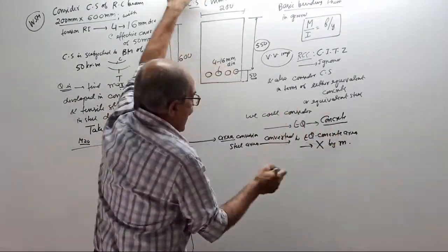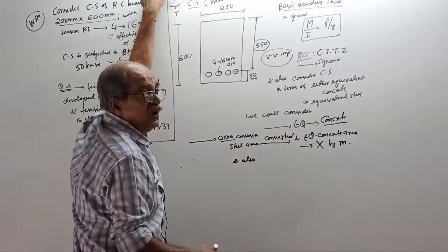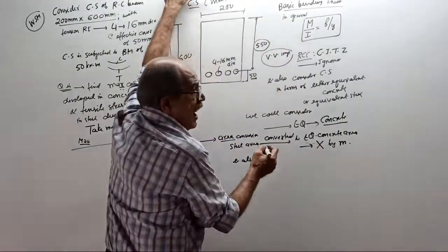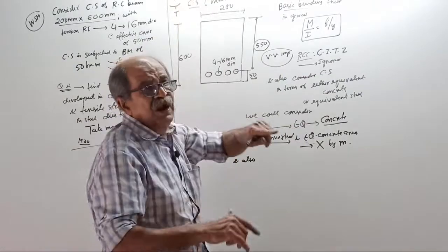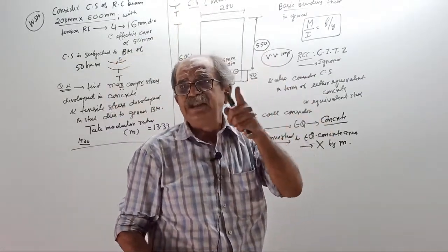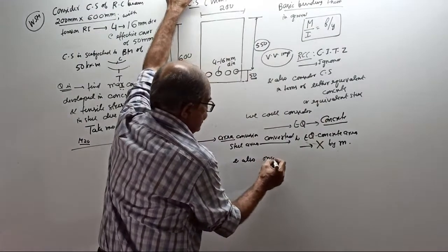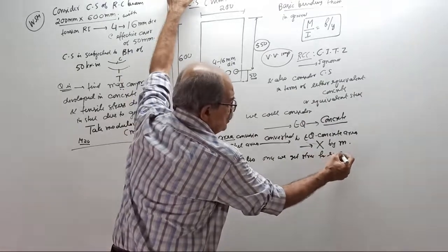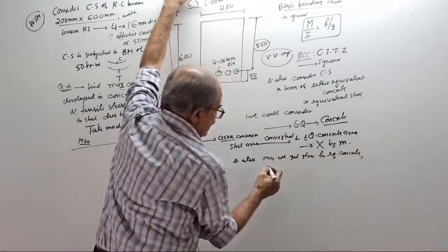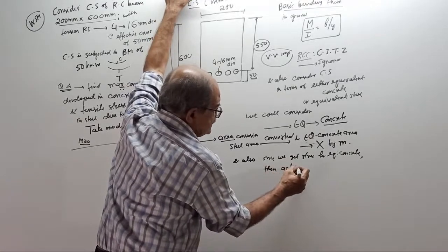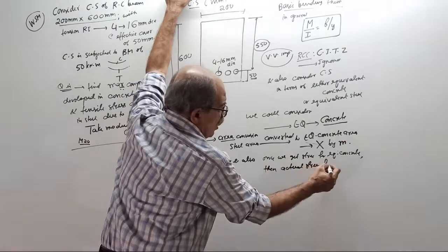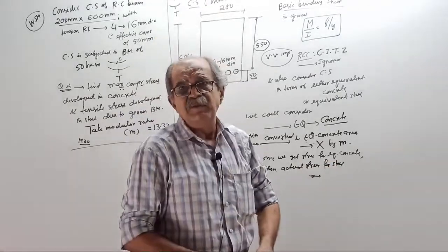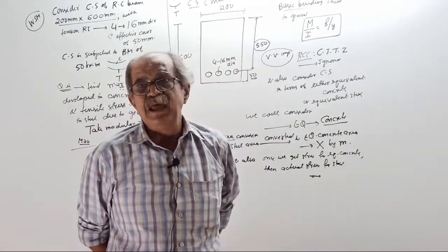Remember, M. And also, whatever is the stress in steel, once we get the stress for equivalent concrete, then the actual stress for steel is what? Tell me. Multiply by M or divide by M.